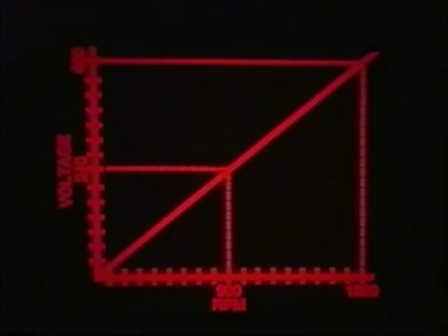In previous presentations, we have covered the fact that the normal reaction of any alternator is to have its output voltage vary directly with speed. Thus, if the prime mover is operating at some speed lower than rated synchronous speed, the alternator's natural voltage will be low.